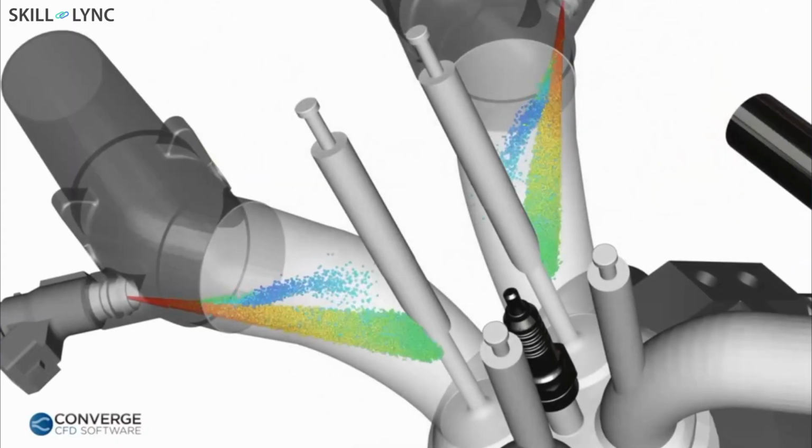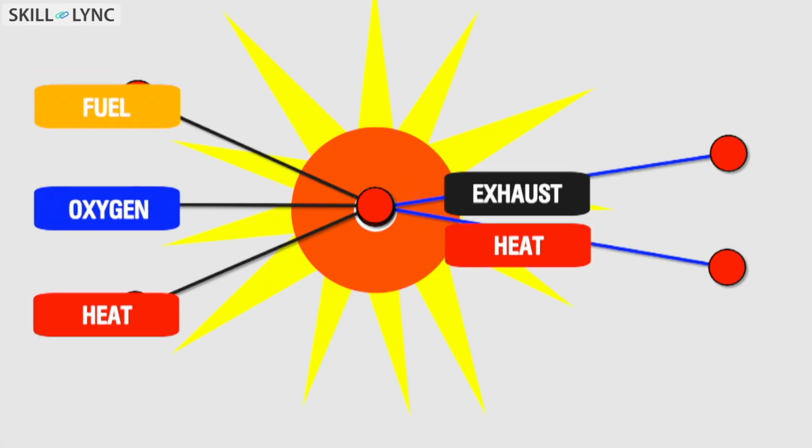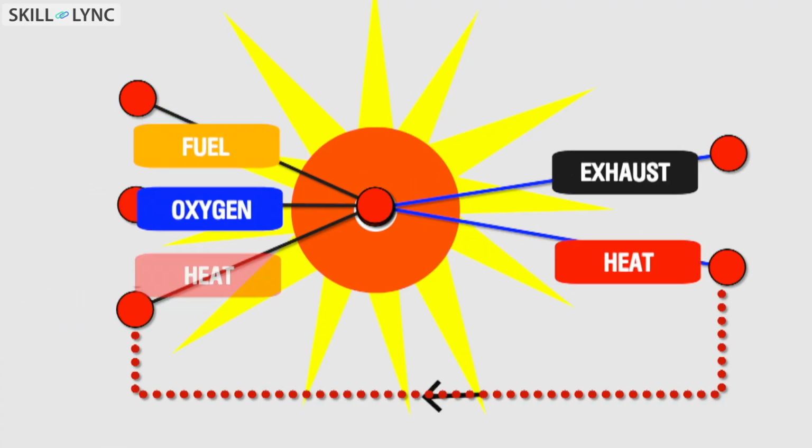Speaking on how boiling points vary due to pressure, there is a similar phenomenon happening in engines, which is technically called cavitation. In this video, we will be discussing how cavitation occurs using a simple example. If you take an engine, the fuel flows in a complex path from the tank to the combustion chamber. During this time, the fuel flows through chambers that vary in curvature, area, and so on. When fuel flows through chambers where the area suddenly decreases, it would result in reduced static pressure.